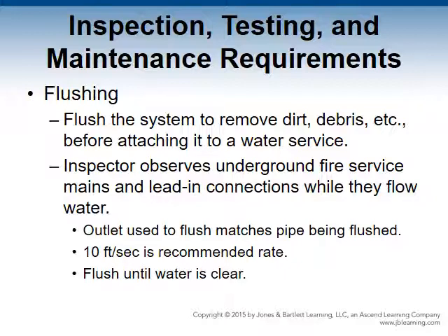This ensures that any size item that enters the pipe can exit it. The recommended flow rate is 10 feet a second. The minimum flow rate should not be less than the system water demand rate. The inspector flushes it until the water flow is clear.